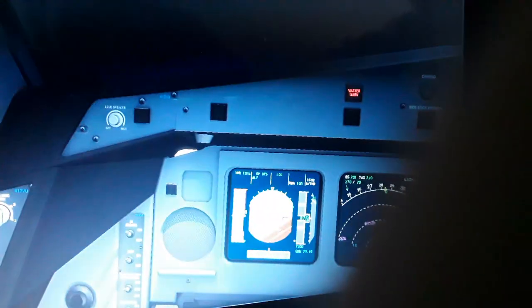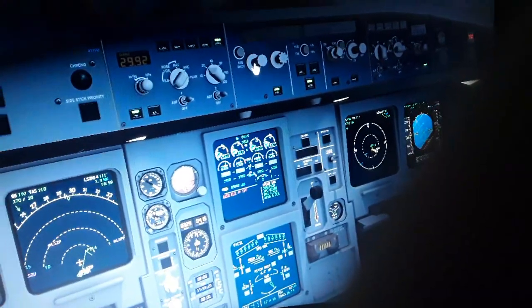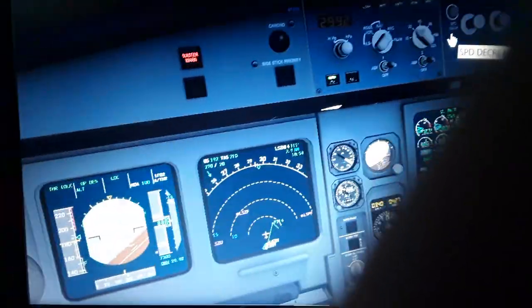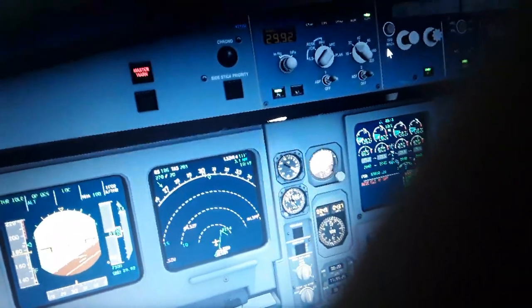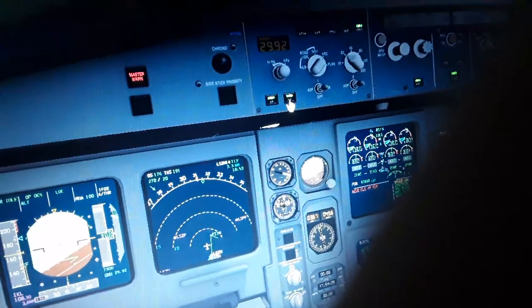Making this approach now, decrease even further the airspeed. Use the LSZH localizer also. The LSZH is on, so keep descending. For this approach we're still a little bit higher, 9,000 feet. We need to extend the flight path a little bit and slow down.